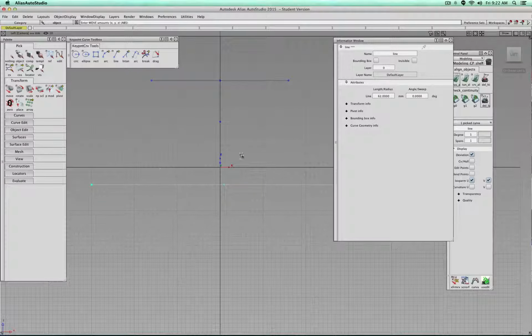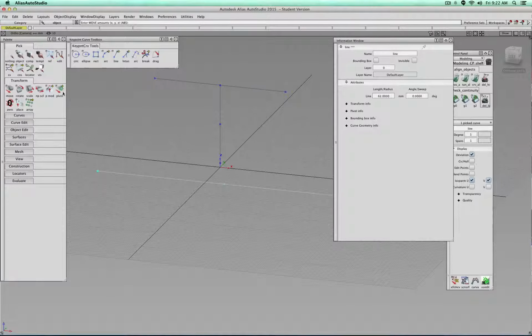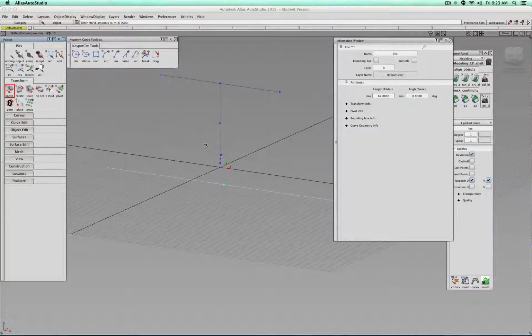Now, if you do not necessarily have everything set perfectly to the grid, I can also, for example, use the pivot point. And FYI, I have my snap subdivision set to 2. So for example, if I Control Alt click onto the line, you see those blue markers. I can snap to the center of the line, the midpoint. Okay, then I can go move.